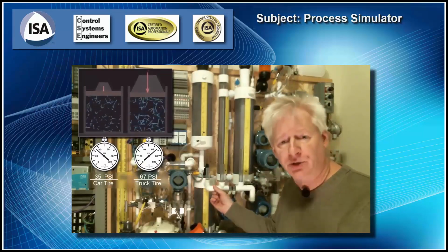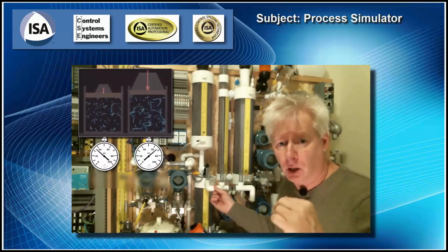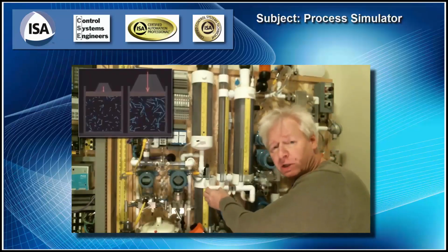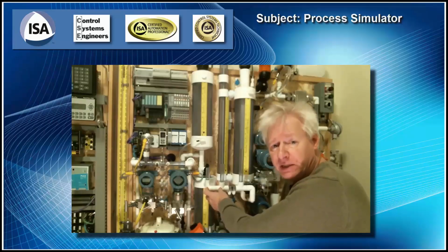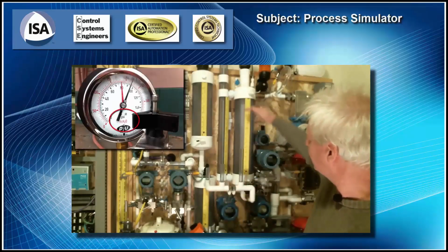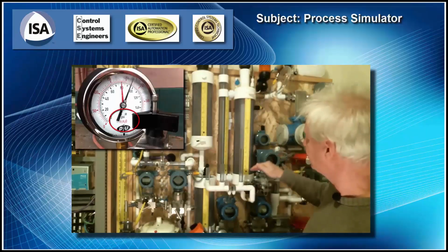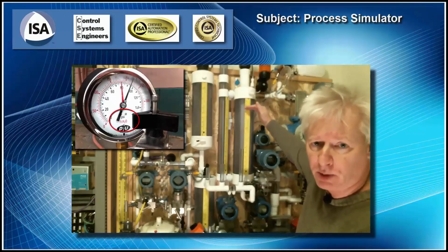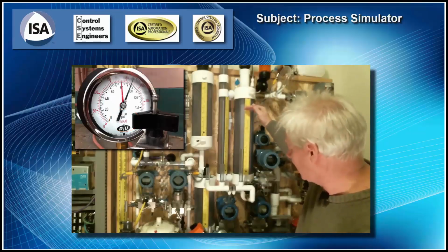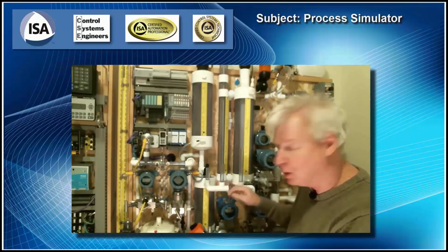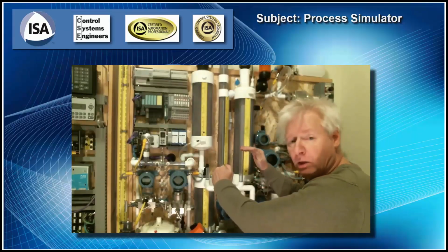And this pounds per square inch will tell us when the pipe's going to rupture or when the gasket is going to rupture. So it's easy to talk about PSI, so our gauges will typically be in PSI and not feet. When we talk about feet, we'll use the feet to measure the height in the tank. So we'll take the pressure, convert it to feet, because that's exactly what we want to measure, is how many feet of water we have. It's potential energy.